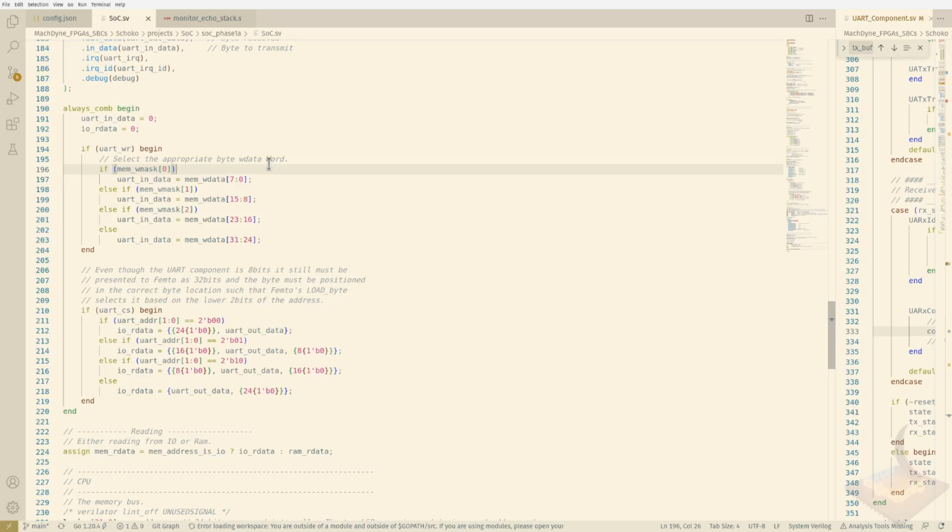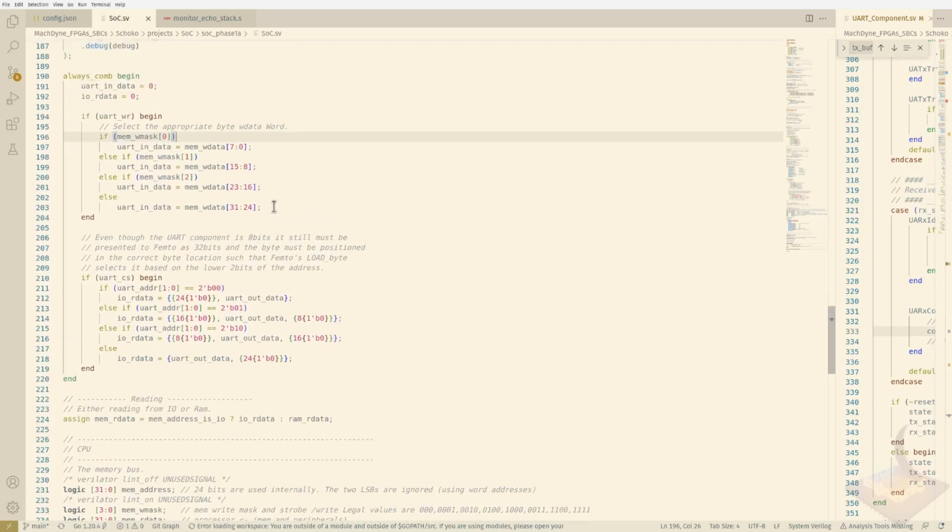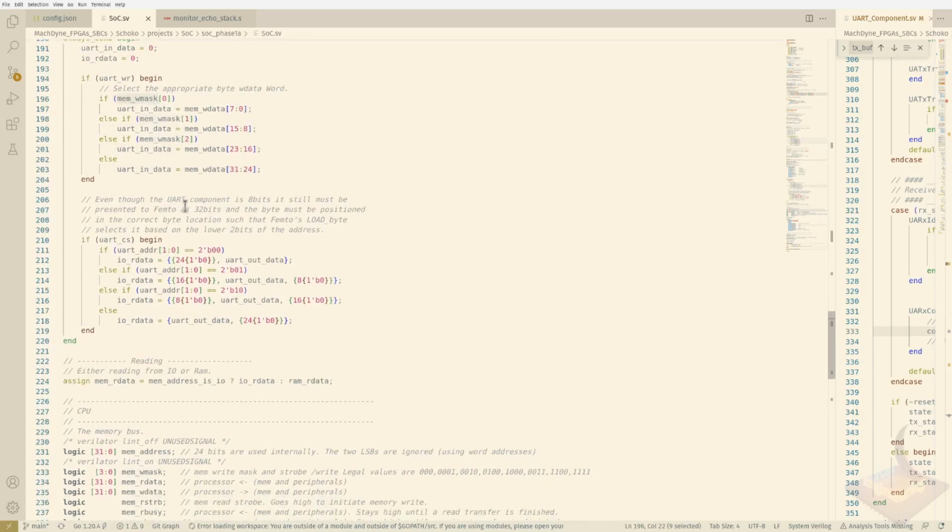because memory on a RISC-V is byte addressable. It's not word addressable. Word addressable in RISC-V is more of a virtual thing, and it shows up mostly in your assembly and in firmware, but RISC-V standardized on byte addressability when it comes to storage. And that's exactly what we're doing. We have to obey that by looking at that write mask and determining what we're going to store in that particular byte in that location.